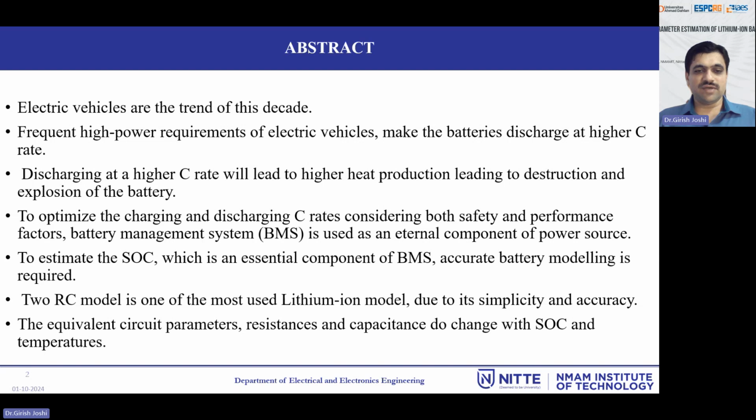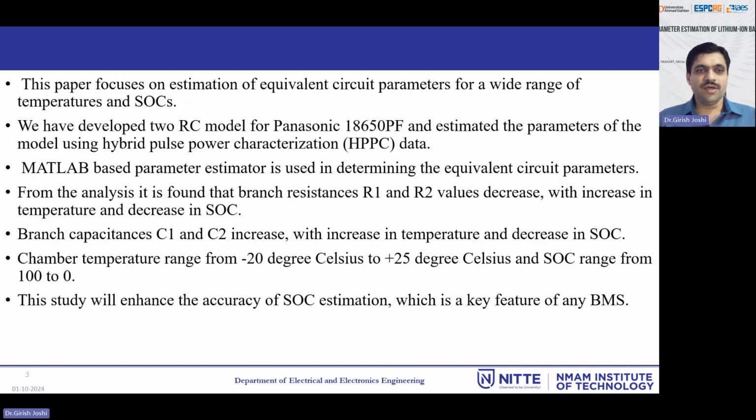The 2RC model is one of the most used lithium ion models due to its simplicity and accuracy. The equivalent circuit parameters, resistances and capacitances, do change with SOC and temperature. That is why we need to estimate these values as and when the temperature and SOC change. This paper focuses on estimation of equivalent circuit parameters for a wide range of temperatures and SOCs.